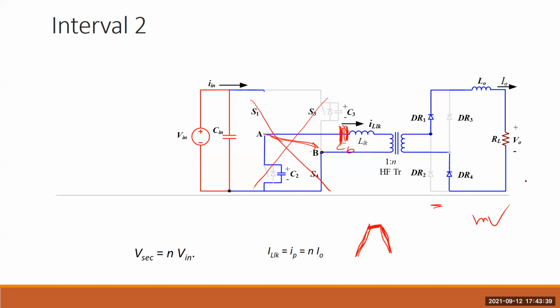If you see that this voltage is quite a bit higher, for example 4 or 5 volts, then you can consider putting a blocking capacitor. That is not due to phase shift, it is due to mismatching of your switching. If it is in millivolts, then you don't need a blocking capacitor, your switching is perfect, and there are no flux imbalance issues at all.